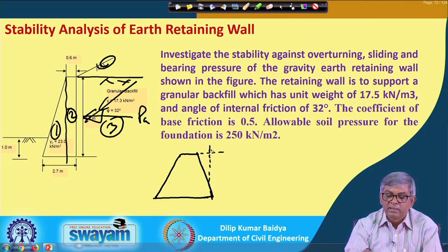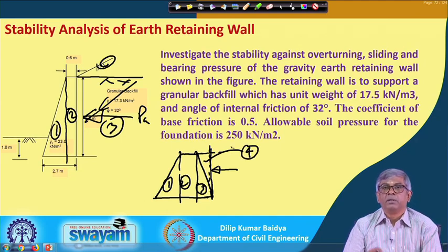I will consider this as the wall, and I will calculate PA acting here. That means I will divide the self weight into parts 1, 2, 3, and the soil weight will also be coming on the wall, assuming I have to consider the weight of the soil also as a fourth part. Then the rest of the analysis will be similar.